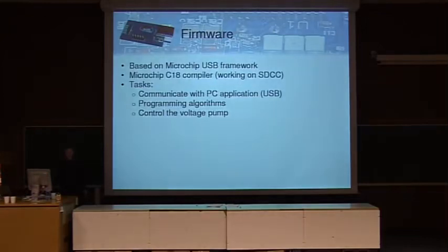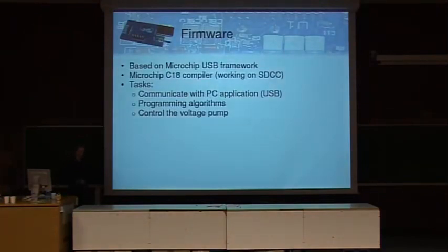The firmware of the Usbpicprog is based on the Microchip USB framework. This is just a bundle of source code with some examples which you can compile, and you can write it into your microcontroller, and it will have some basic USB functionality like bulk reads and writes. And you can just continue using that framework and make your own tasks in it.